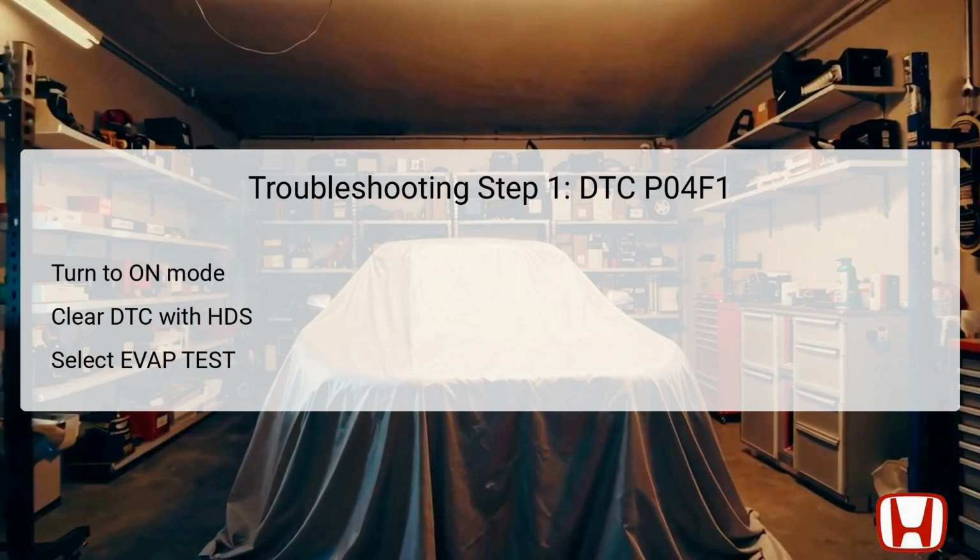If the test results display OK, further investigation should focus on exploring potential intermittent failures, such as loose connections or corroded terminals at critical components like the FTP sensor or purge valve.